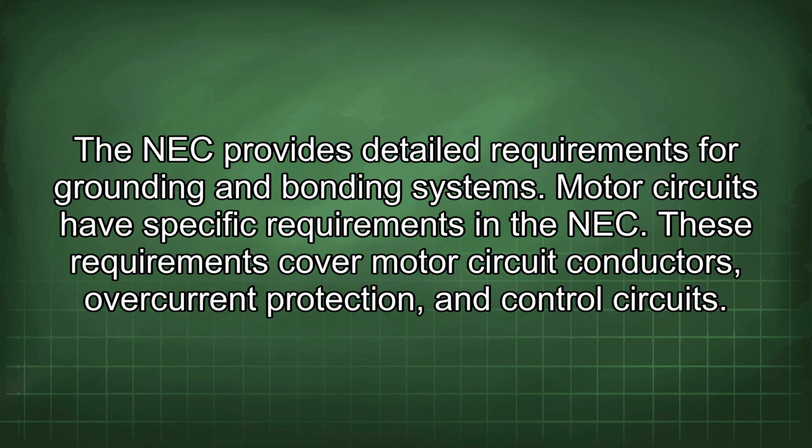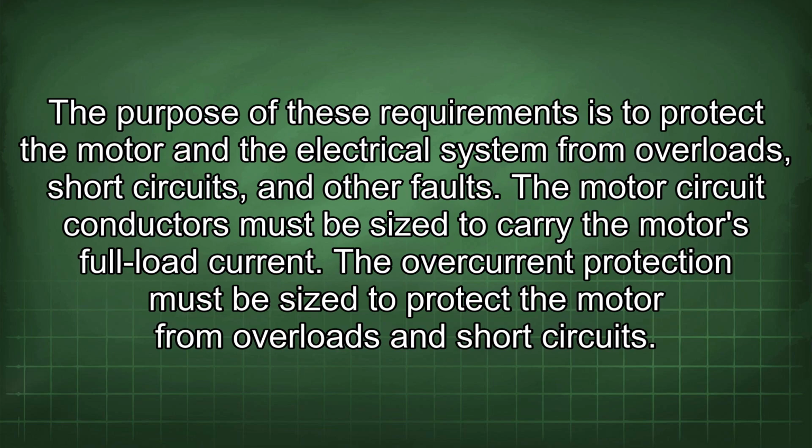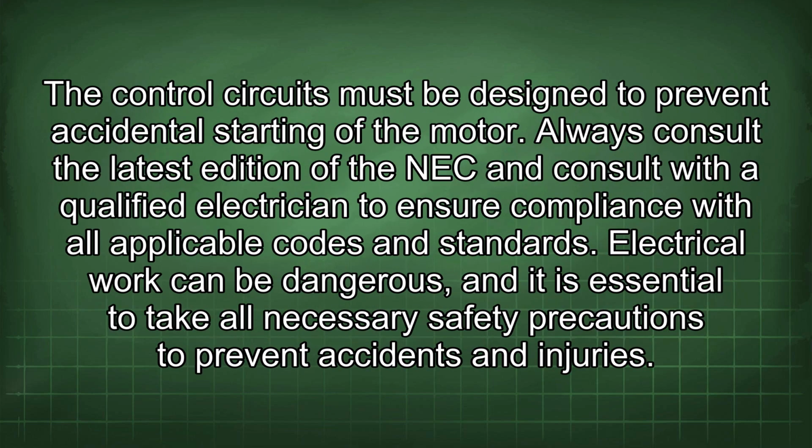Motor circuits have specific requirements in the NEC. These requirements cover motor circuit conductors, overcurrent protection, and control circuits. The purpose of these requirements is to protect the motor and the electrical system from overloads, short circuits, and other faults. The motor circuit conductors must be sized to carry the motor's full load current. The overcurrent protection must be sized to protect the motor from overloads and short circuits. The control circuits must be designed to prevent accidental starting of the motor.